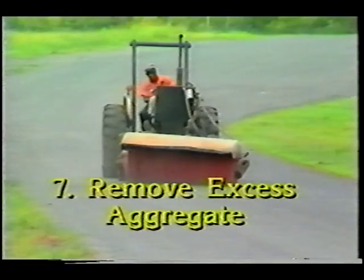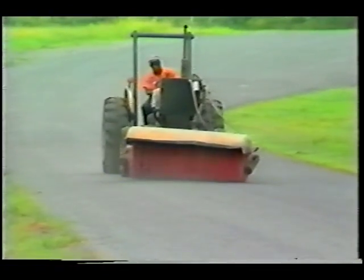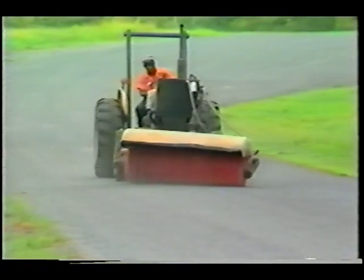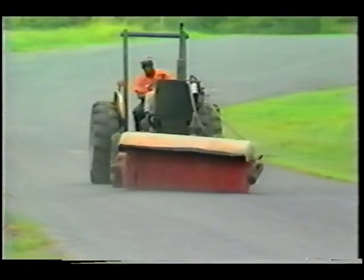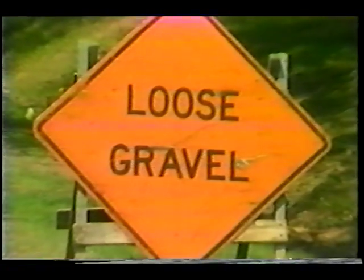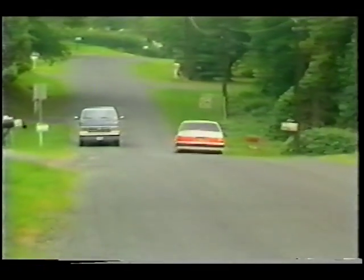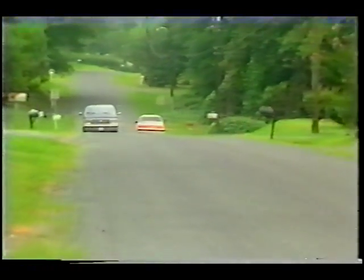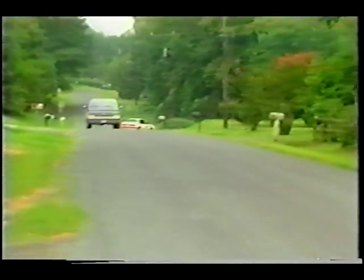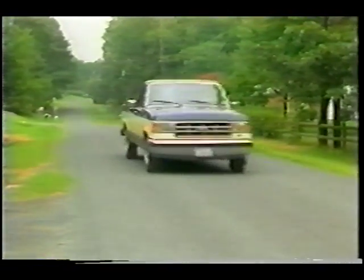Step 7, remove excess aggregate. If necessary, remove excess aggregate by lightly brooming the surface. Placement of reduced speed and loose gravel signs is recommended when the road is open to traffic. By following these 7 steps, an effective asphalt chip seal can be installed and provide a better road for the traveling public.